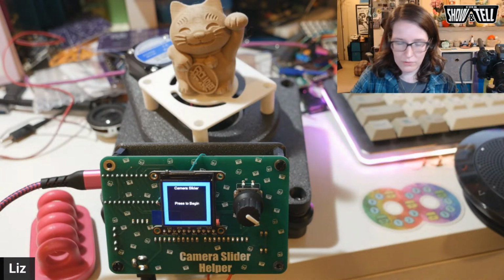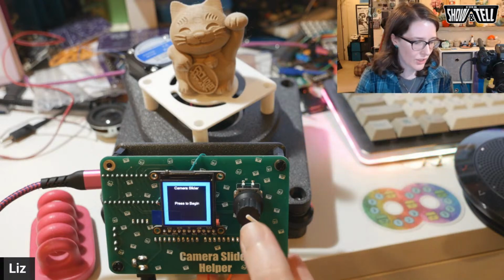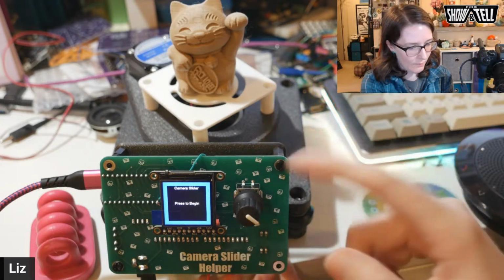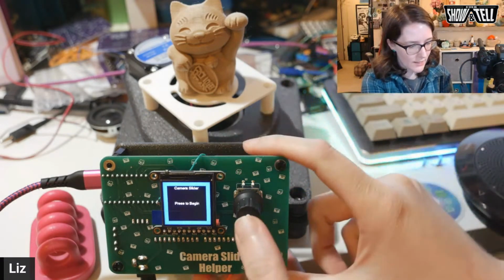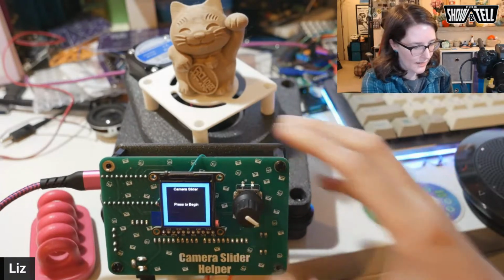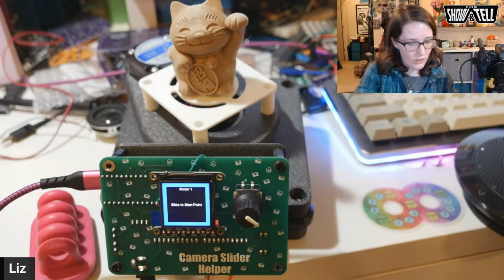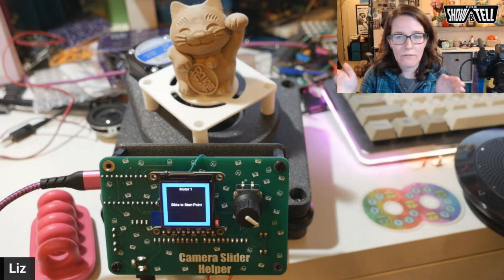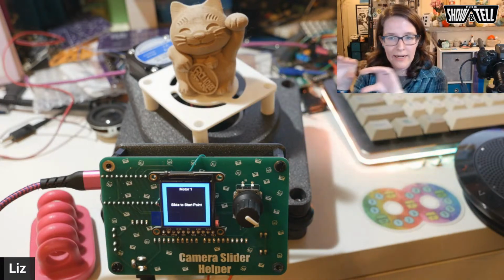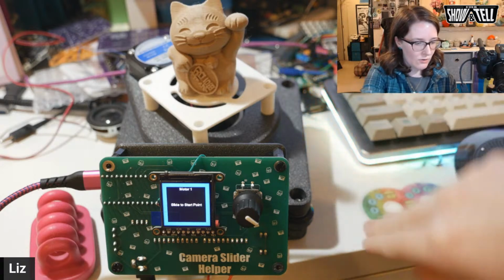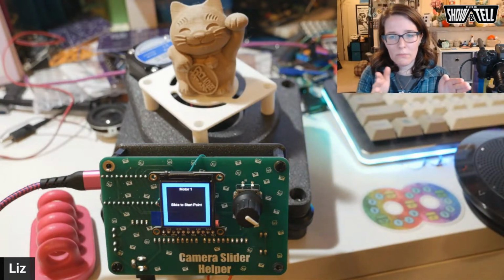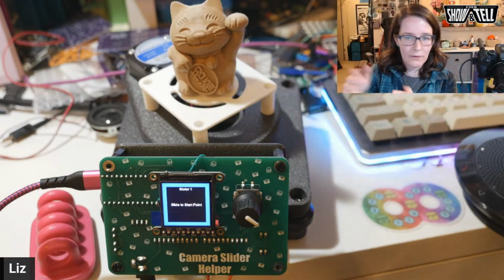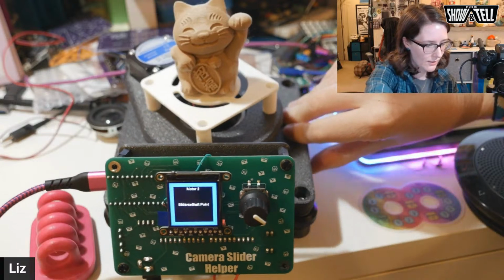So I can just show basic functionality that's locked in right now. We have this rotary encoder and a TFT that's connected over SPI, and you press to begin. And then there are 2 end stop buttons on either side that control the path for the motor that's actually sliding the camera on the rails. To choose where the motor is starting, you'll hit it with the end stop. So I'll just press this one on the side here.